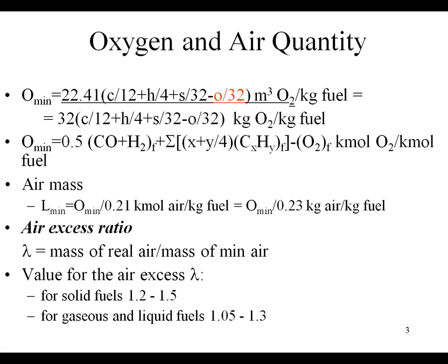Normally, when you run a combustion, we are speaking also about the burners, and the burners are also low combustion NOx burners, meaning that in these burners some methods are taken in order to avoid the formation of NOx, NO2, or NO. And this is done with a value of the air excess ratio less than 1, because NO is coming from a reaction of N2 plus oxygen, giving NO, with some coefficient here.